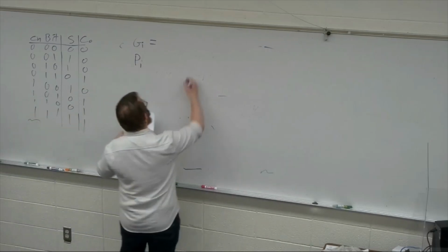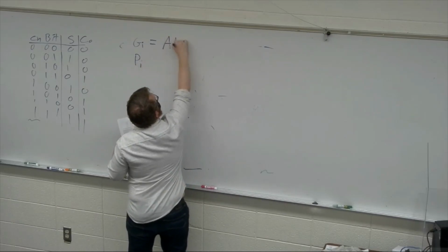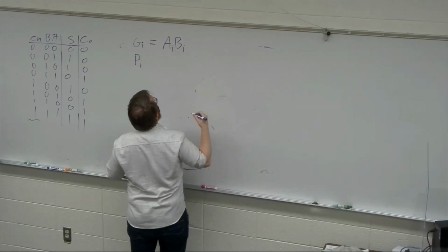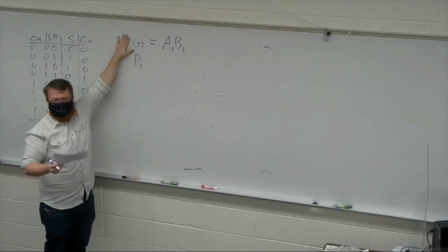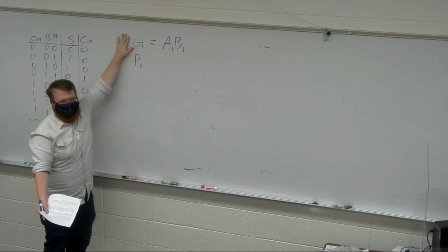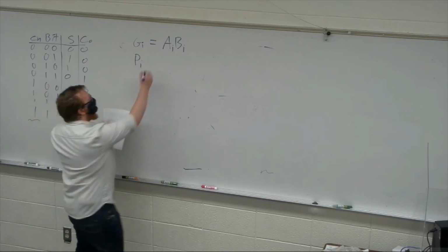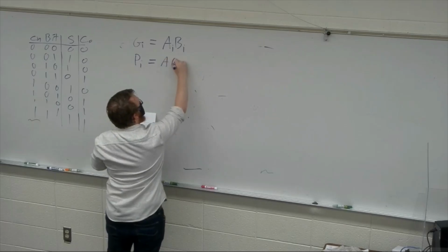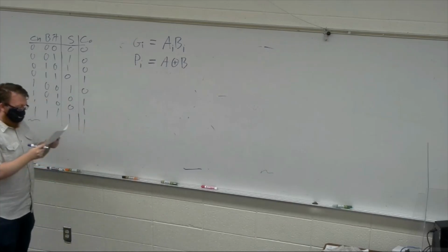So if I generate an I using the half adder trick, well, and actually this is true in either one, really, but we'll focus on, right? Generate is just A and B. I know that I made one because I'm not having to worry about a carry in, because that gets handled by the propagators. So then the propagate needs to worry about, again, in the simplest case, A XOR B.